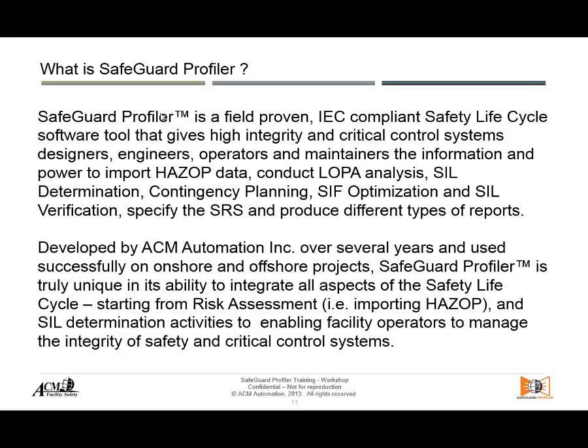Once you understand what is going on, you can leave it in the background, and you trust that it's working correctly, because this tool is complying with the IEC 61511. So we can concentrate on building and doing the engineering. And then we create the safety requirement specifications in the tool. So the SafeGuard Profiler allows us to put all that information in there, so that it can be used later on, including different types of reports that I was talking about. Reports specific for operations, for example. Reports for maintenance. Reports for management, for the functional safety management.